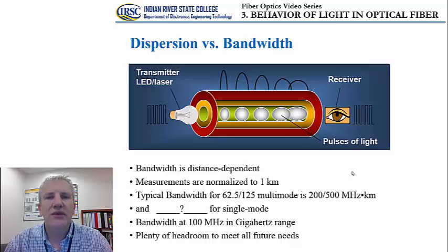And then we also talked about a few important concepts that are related to how the light is being kept inside the optical fiber. We have talked about, again, total internal reflection and the critical angle. We also defined the acceptance cone and numerical aperture. All those are important terms that need to be specifically described or defined for a specific optical fiber to be able to transfer the information from one end to the other.